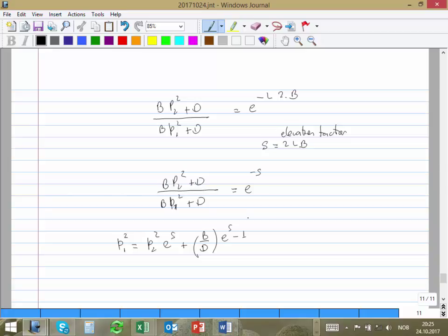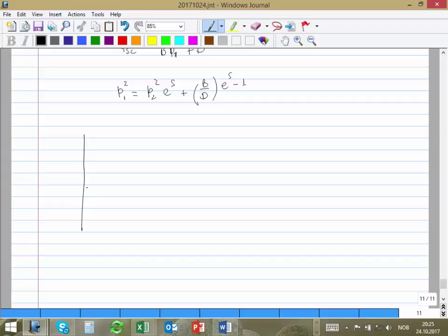What are we looking for? Remember, we are looking for an equation, so don't lose the perspective here. We want an equation in terms of Q at standard conditions. We are calculating from the wellhead all the way down to downhole. So which one is P1 and which one is P2 in that case? Okay, we have our well. Again, I'm going to draw, this drawing is not going to go away. I'm going from P wellhead all the way down to PWS, countercurrent, so I'm looking for an expression.